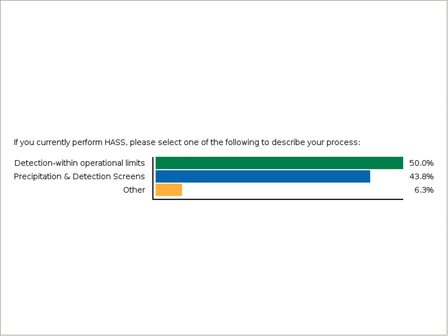So we'll give you all about 30 seconds to click there and let us know, and we'll show you all the results of that as well. I have found that there are situations where products have very clear operating limits that are simply due to temperature limits on a component where a microprocessor just shuts down. It's not going to work. But you don't hit any destruct points until far after that. So a two-stage screen makes a whole lot of sense.